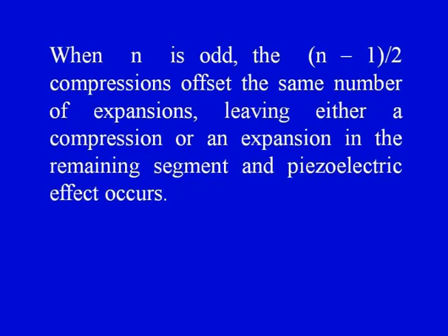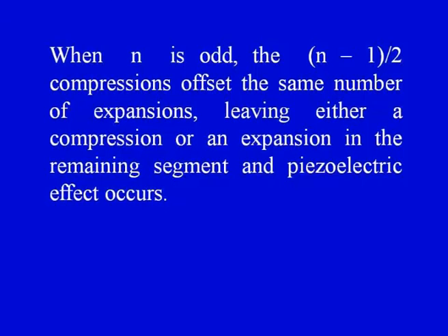When n is odd, the n minus 1 by 2 compressions offset the same number of expansions, mutually cancelling out, leaving either a compression or an expansion in the remaining segment, and the piezoelectric effect occurs. So, that is the technique of working on high odd harmonics. One can generate ultrasounds of pretty high frequencies.